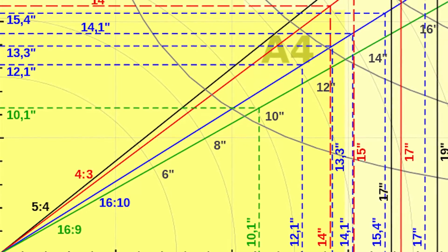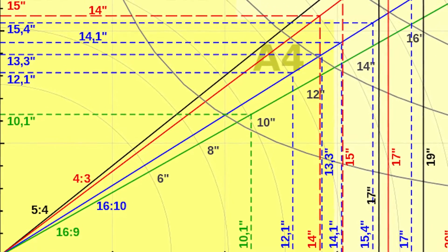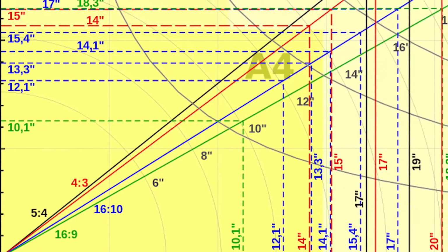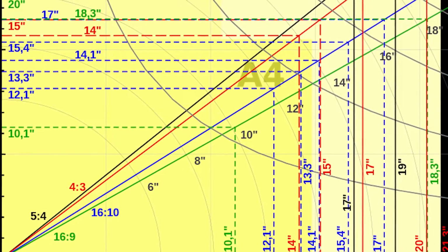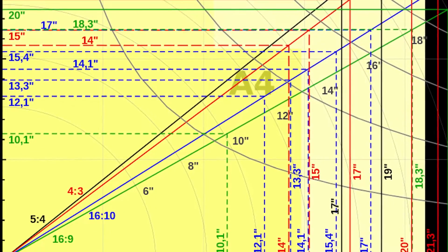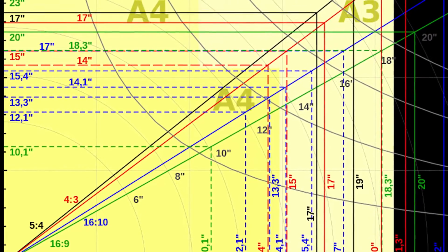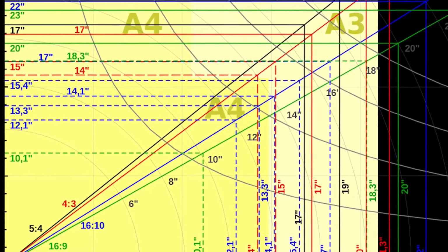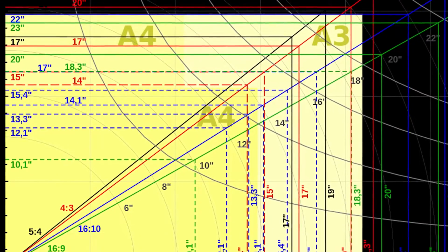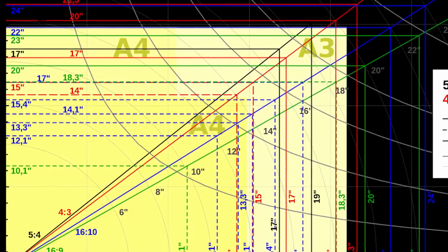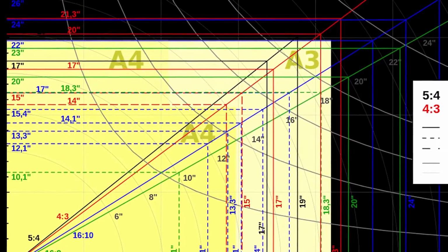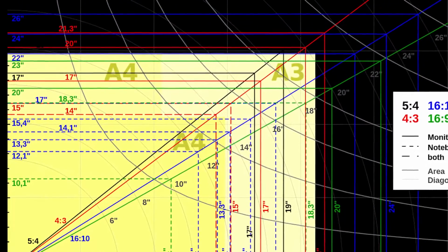HDMI is designed to make use of standardized aspect ratios such as 4:3 or 16:9. In the case of our RGB output, the scaling process must include an aspect ratio change in order to prevent dark spaces on the sides of the 1080p picture. Another alternative might be to use up all of the horizontal real estate and chop the bottom of the picture off completely.